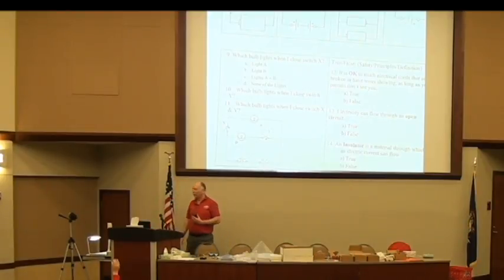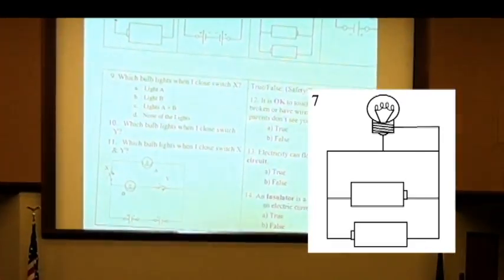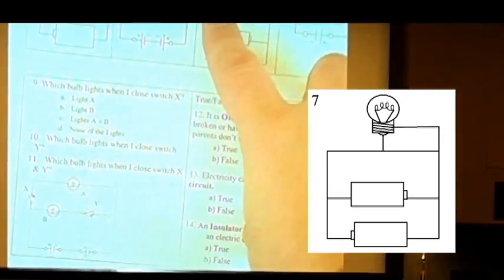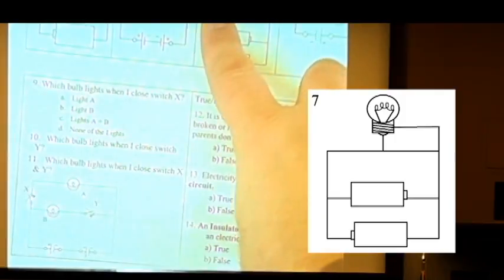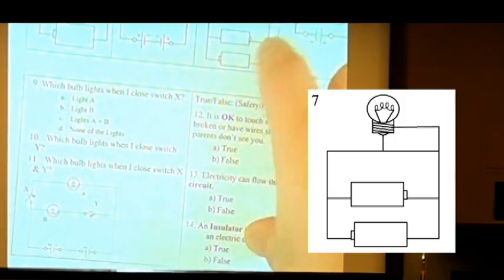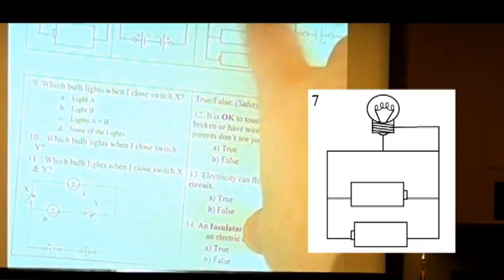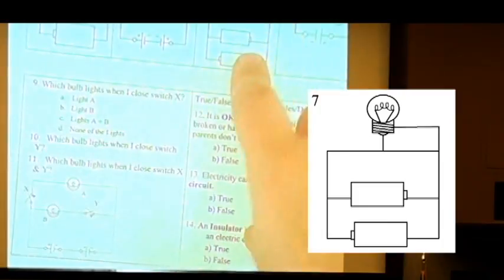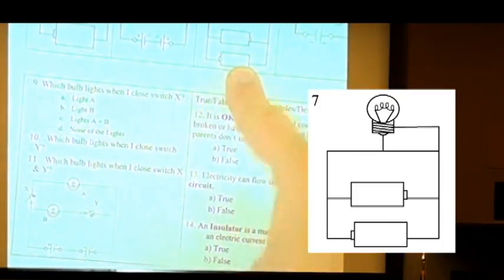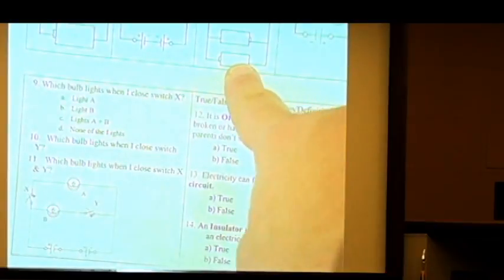Short circuit. Very good. What will happen is electricity takes the path of least resistance. Wires have a lot less resistance than light bulbs. I have a short circuit here, and basically the electricity, if it was going to go around correctly, would go around here and come down and would skip the battery. It's going to take the easiest circuit it can to get back home. So you've got to look for that. There will be some questions about short circuits and how they affect it.